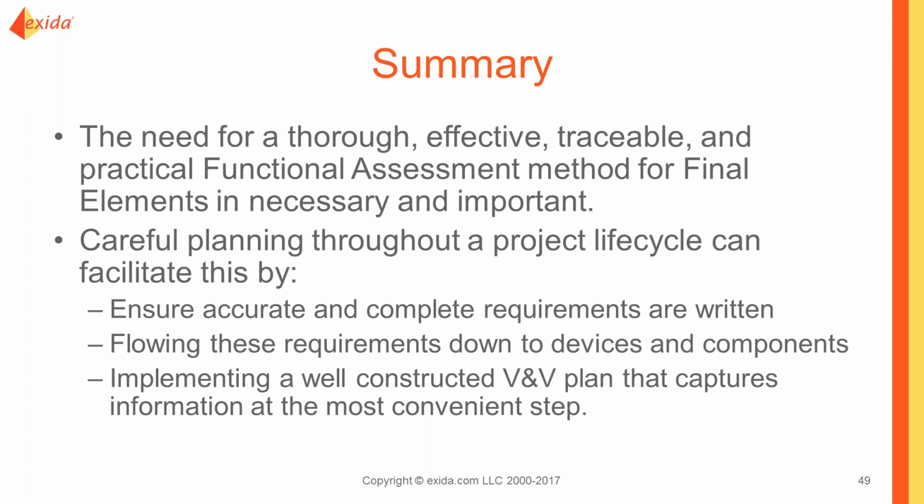Because frankly, if you can do a stroke test at the valve integration house, it might be quite a bit simpler than doing it on site. So planning out the V&V activity can make it much more possible and practical to get good functional safety assessments of those final elements.